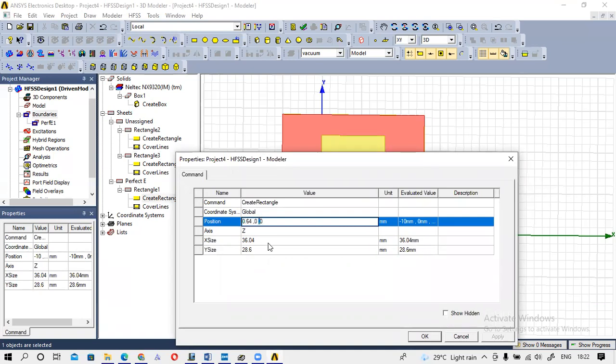And y-axis I move 2.4, that is the high impedance line section width. And the position should also be 0.762, otherwise it is not on top of this plane. So that position should be there.